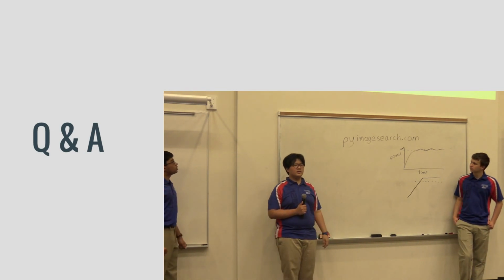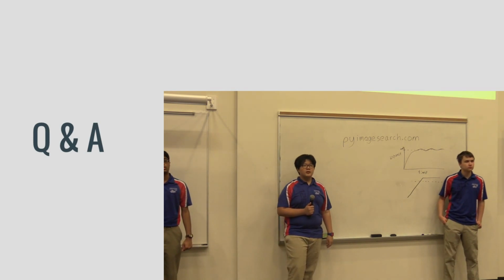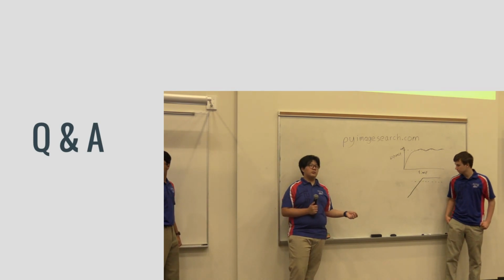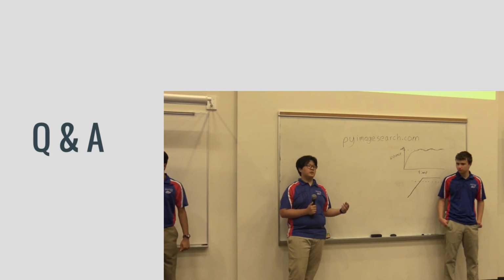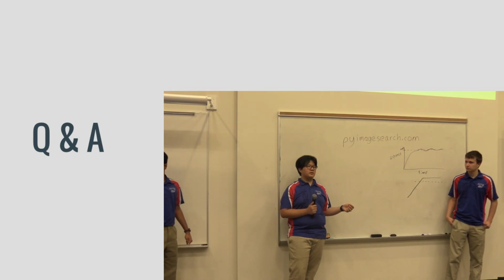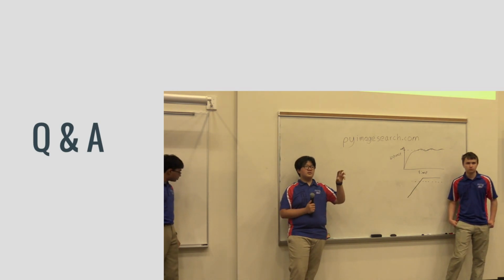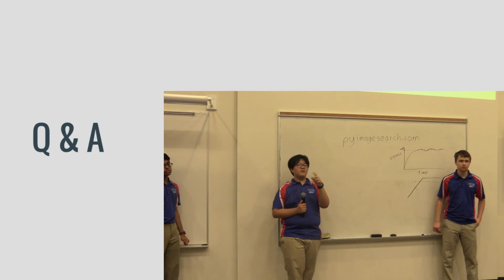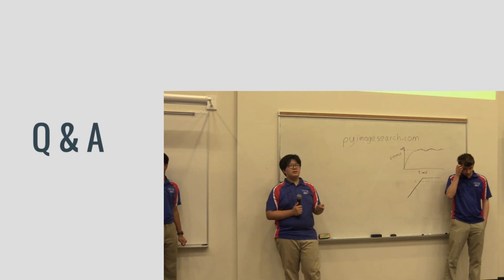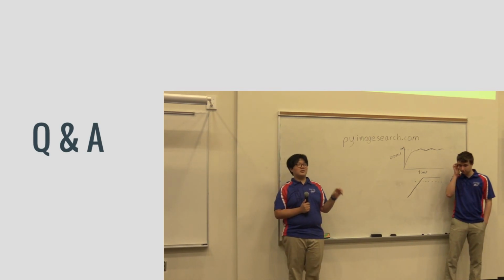The second step is tuning our offsets. We took our robot to a practice field, and we had the drivers manually set up some shots that we knew we were going to hit. We recorded the camera positions of those shots. We recorded the position of the target, and we recorded the center of the camera. We compared those two offsets, the X and Y offsets. Using a bunch of data points, we created a graph, and from that graph, we made an equation.